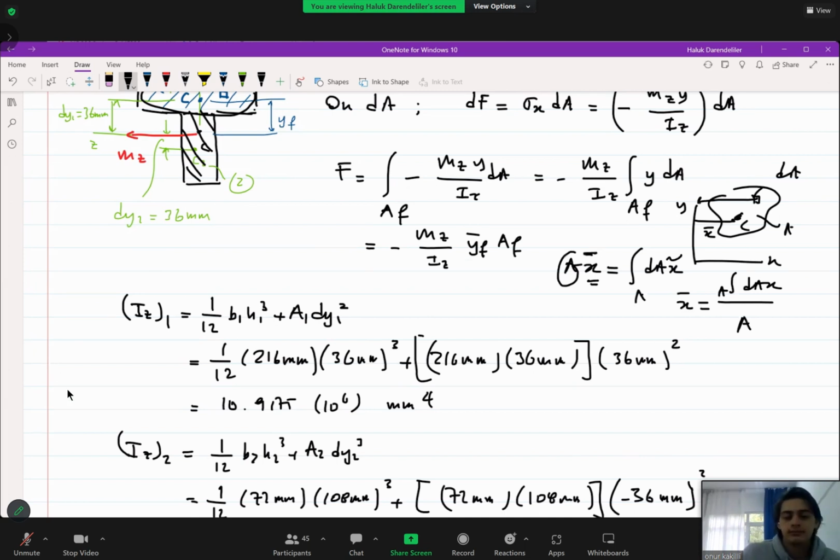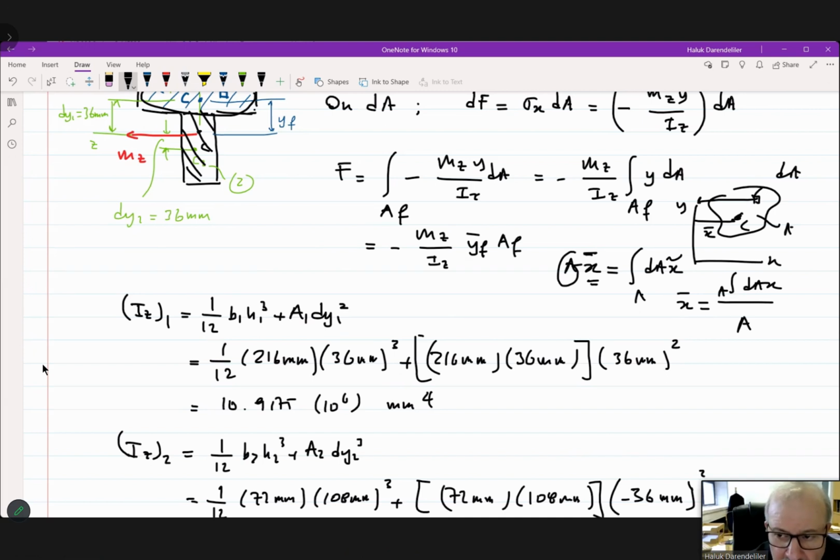Shortly, first moment of area, of course, using the proper coordinate systems, gives you the location of the centroid. And that equation is the integral of dA times x over the area, divided by the area. Clear? So please look at the statics book for this, but we use this equation for the centroid.